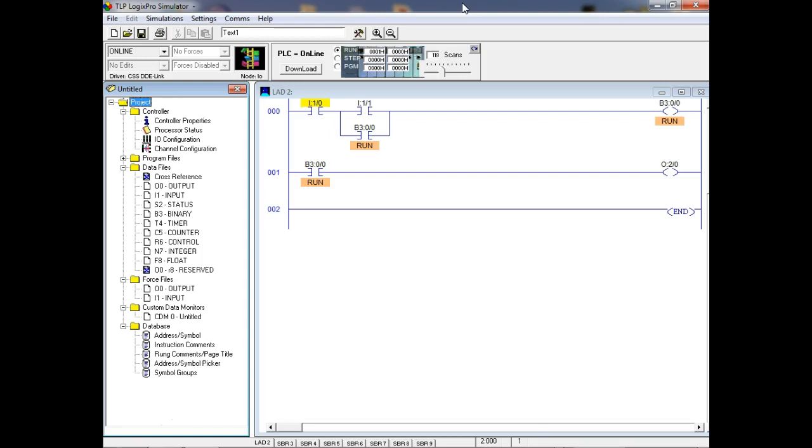What you do is you can turn the light on each time with the push button, but you're also going to have to implement the counter because you want it to do it 3 times. If you just did it with the push button, I can do it 15 times. That makes sense? So your push button can do 2 things. It could turn the light on, but it's also going to increment your counter. And then you're going to use the counter contact down here. You press it 3 times, then it does what? It'll stop no matter how many times you press it. So the light will only come on 3 times. Does that make sense?